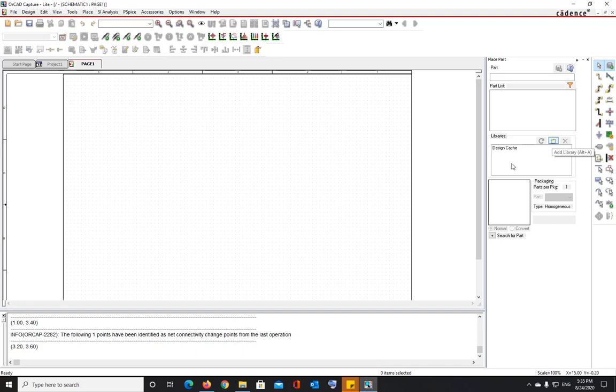Here you're going to add different libraries where you keep different components for the electric circuit. The most commonly used libraries are the analog library and the source library. Analog library is where you will find your resistors, capacitors, inductors, and some other components, but most of the time you're going to be using these three components from the analog library: resistors, capacitors, and inductors.